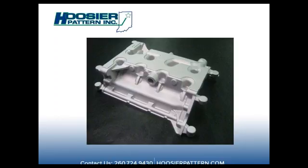For production 3D printed, you can even have them fit into a horizontal or vertical molding. You just print the piece, set it into your core print on your DISA or your Robertson or your Hunter. So creativity by the foundry engineer is going to be the limiting factor on how you apply this to your situation.